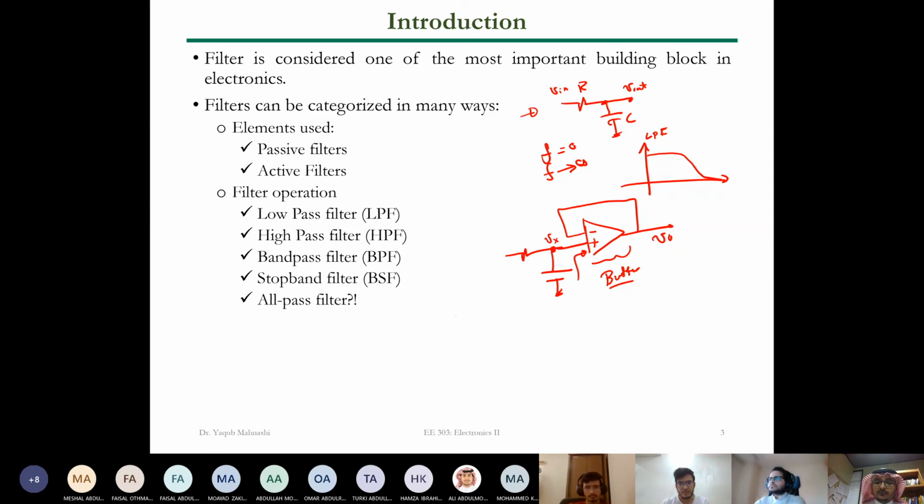What about this circuit here? Can I change the buffer to R1 and R2? What do you think, guys? Can I do this? Yes. We have gain. Okay. Input impedance is still infinity. We are okay. And I am adding what? Gain to the filter. So I'm not only filtering, I am filtering and amplifying at the same time.